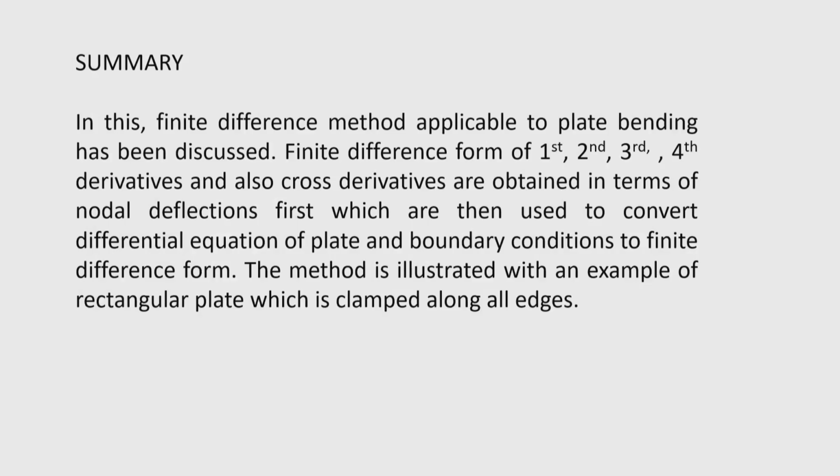The finite difference forms of first, second, third and fourth derivatives and also cross derivatives are obtained in terms of nodal deflections first, which are then used to convert the differential equation of the plate and the boundary conditions to finite difference form. The method is illustrated with an example of a rectangular plate which is clamped along all edges.